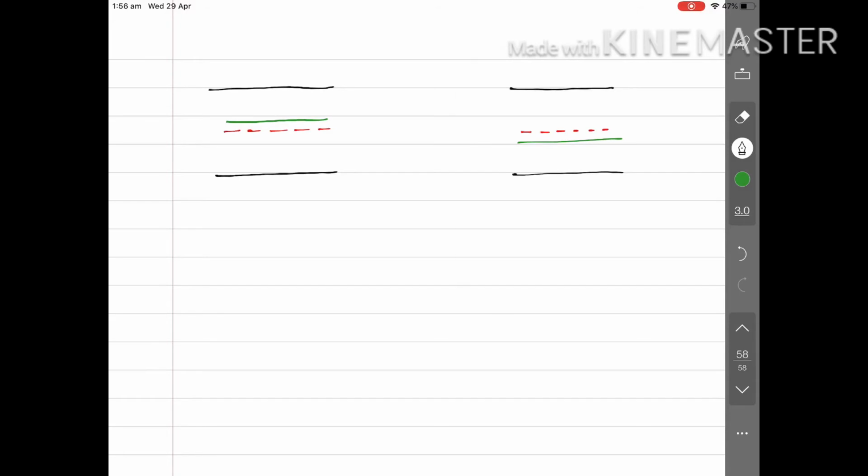Here the same energy diagram is shown. Let me consider this for the p-type. Sorry, this is for the n-type. Why? Because the Fermi level is above the intrinsic Fermi level. This red dot is the intrinsic Fermi level, EFI. This is the valence band, this is the conduction band. Similarly here, this is EFI, this is the conduction band, and this is the valence band.